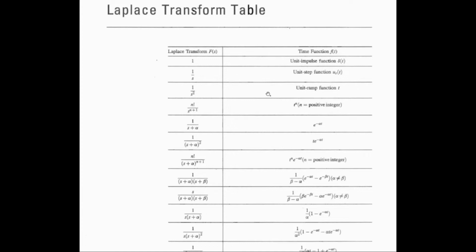That means if you have a parabolic input as opposed to, say, a unit ramp input, a parabolic input will give us this equation. So if t squared is our input, then we're going to end up with 2 times 1, which is 2, over s to the power of n plus 1, which is 3. So you're going to end up with 2 upon s cubed, for instance.